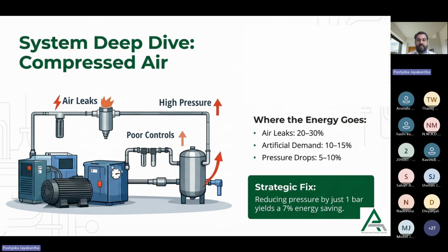So why is regular maintenance important? If you do not regularly maintain these compressors, it can block the air filters. Air compressors use these filters to remove contaminants such as dust, oil particles, moisture, and a clean filter ensures proper airflow into the compressor system.